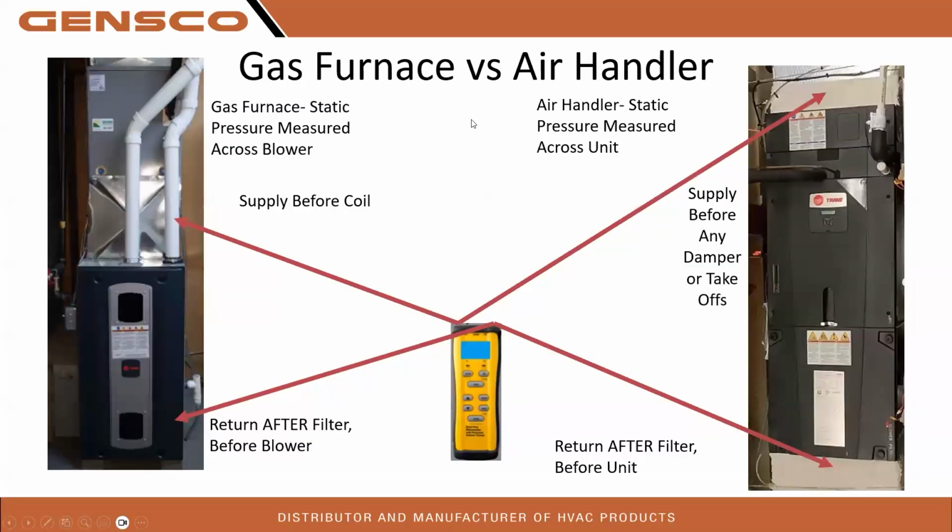There's a little tech tip that if you've called in for me, I may have sent this out to you. This is just a really easy example of what you're seeing as far as where am I measuring my airflow. You can see there is a massive spacer between that coil and that furnace. You're probably not going to get that most of the time. You're going to have to find a way of drilling a small little hole in the side of the cabinet.